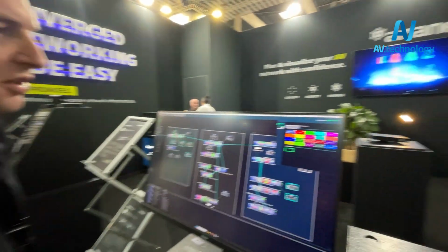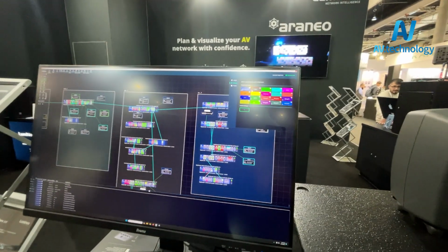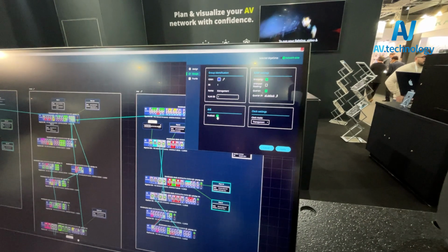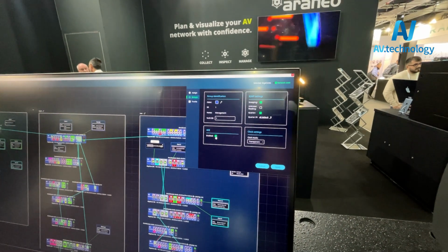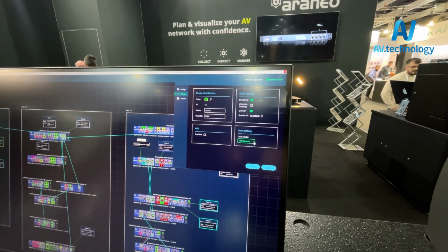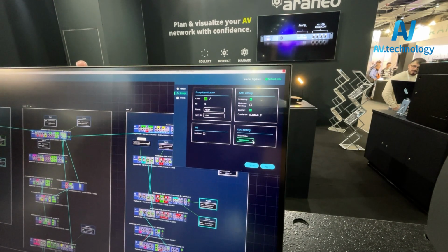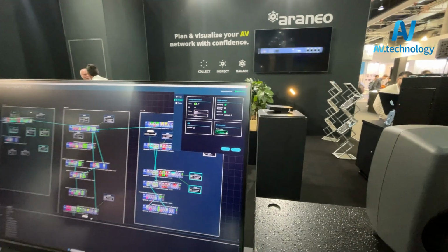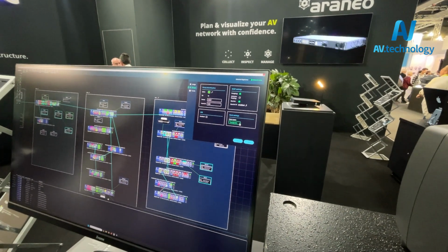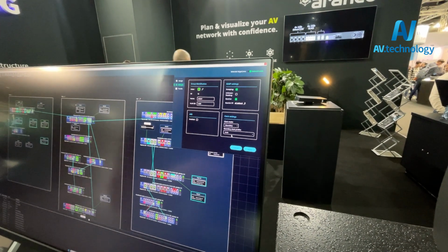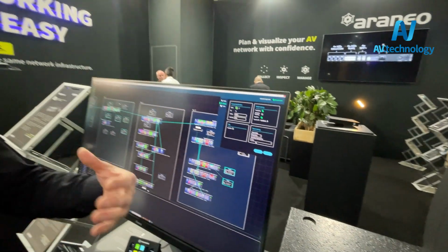If we look at specific group settings, we have just one tick box to enable AVB Milan, so that's very easy. If I have an AES67 group, for example, we do PTP v2 clocking, which means that your clock protocol on the network stays very, very accurate. Up to now, we did this only in transparent mode, but here at the ISE exhibition, we are launching our boundary clock. Boundary clock means that the switch is going to replicate the clock in the network, so it scales to many, many endpoints in that way.